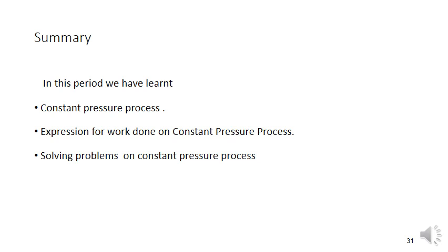Coming to the constant pressure process. Here the energy is supplied, so the gas is expanded from state 1 to state 2, with the pressure constant. We are taking a piston cylinder example. We give heat continuously, the system moves and the volume continuously increases. If you remove the heat, the temperature decreases and the volume of the system decreases. The work done when heat is supplied is the integral of P dV; when heat is rejected, it is minus P dV.